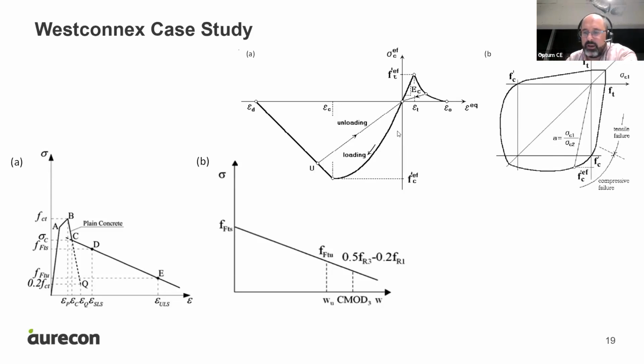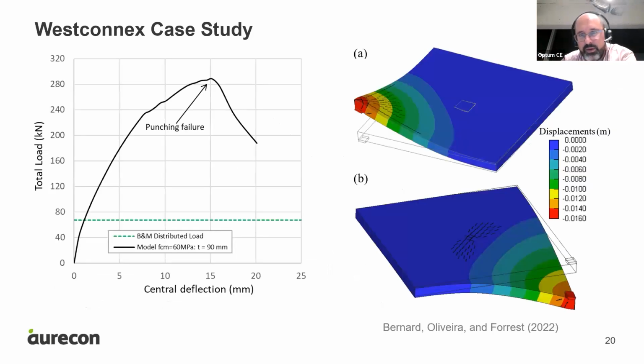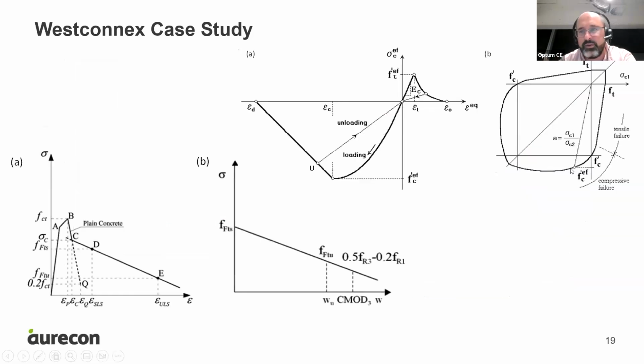How it develops in the modeling is a pure result of the boundary effects. You have symmetry planes here, so once it tries to deform laterally but is restrained, it starts developing stresses in that direction. But the constitutive model uses these biaxial and triaxial enhancements, for which you have equations available in design codes like Eurocode or fib Model Code.